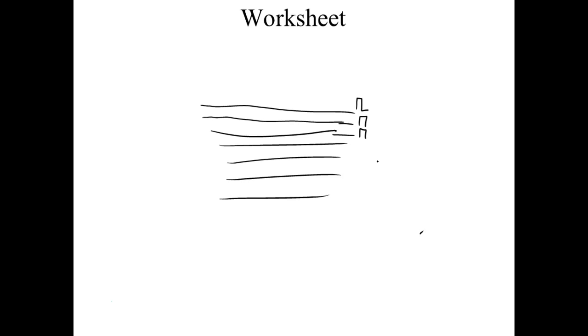Does this make sense? Now when we get down to the bottom, we need to send two sync pulses. We need to say, okay, I finished the line, and we need to have another input saying I finished the picture, right? Does that make sense? So we have what we call vertical and horizontal syncs on our video.